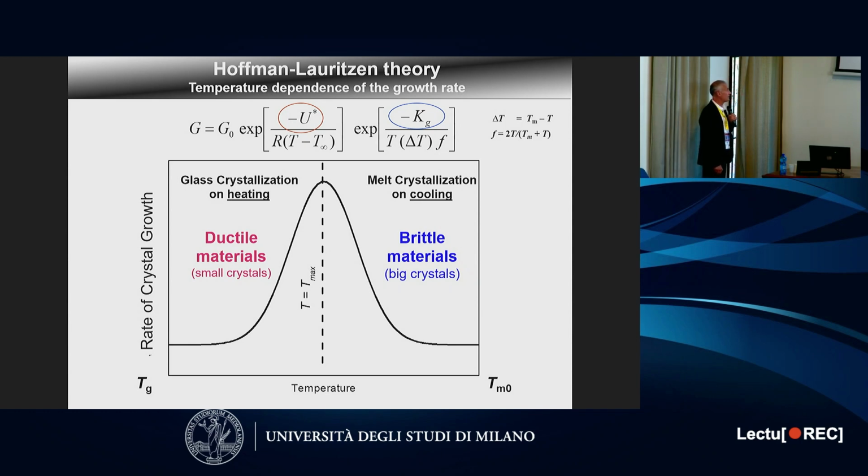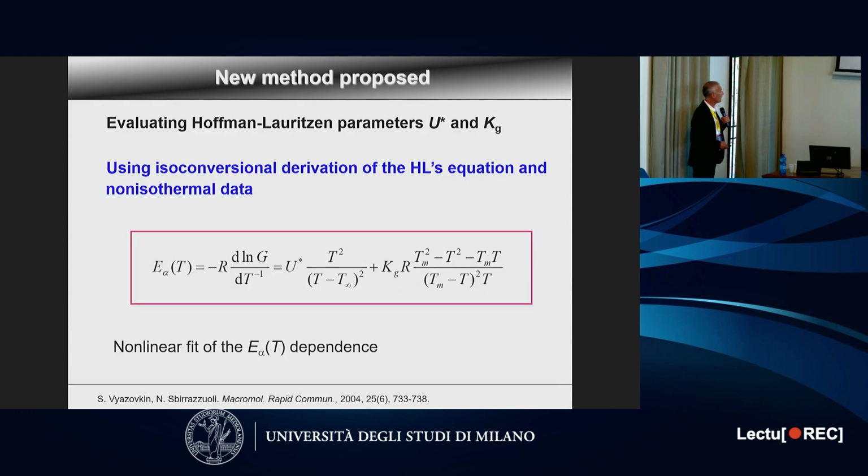It is very interesting because in that case, we have a very good link between the theoretical aspect and the industrial application. I will not go into detail, but you all know that here the sizes of the crystals are different and the properties of the polymer are different. And here you have bigger crystals, but not the same properties. And it also corresponds to industrial processes like extrusion. And in this region, you make the stretch blow, for instance, bottle blowing. So this is very interesting also.